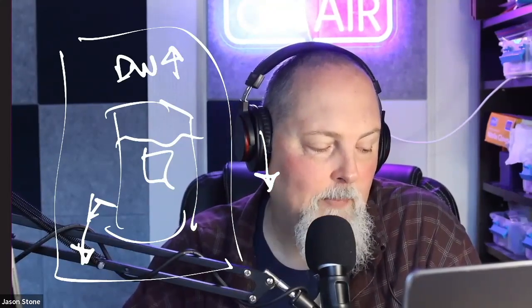If we have a rupture in one of the pipes and water starts pouring out, reactor water level goes low, but also drywell pressure goes up. So more than one instrument, of different types, can tell me something's wrong. I can set up a logic system that says, if I get a reactor water level and a drywell pressure, then make this happen.